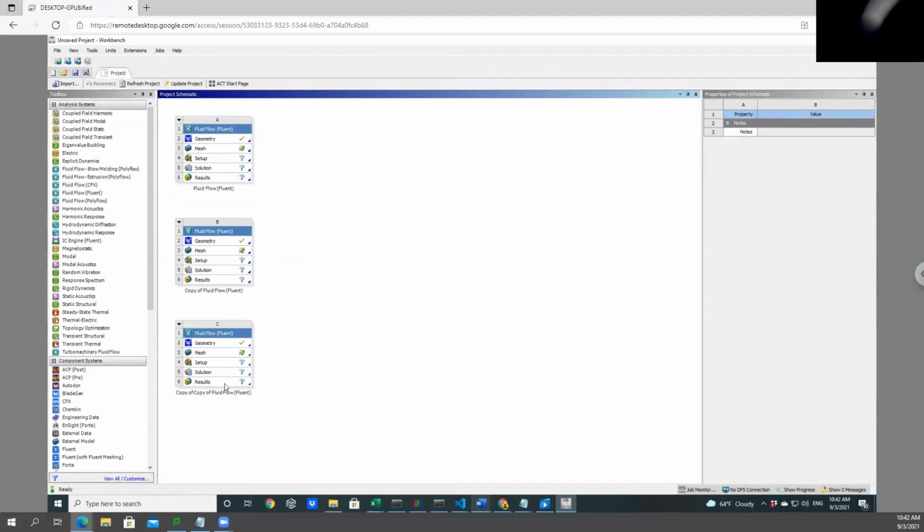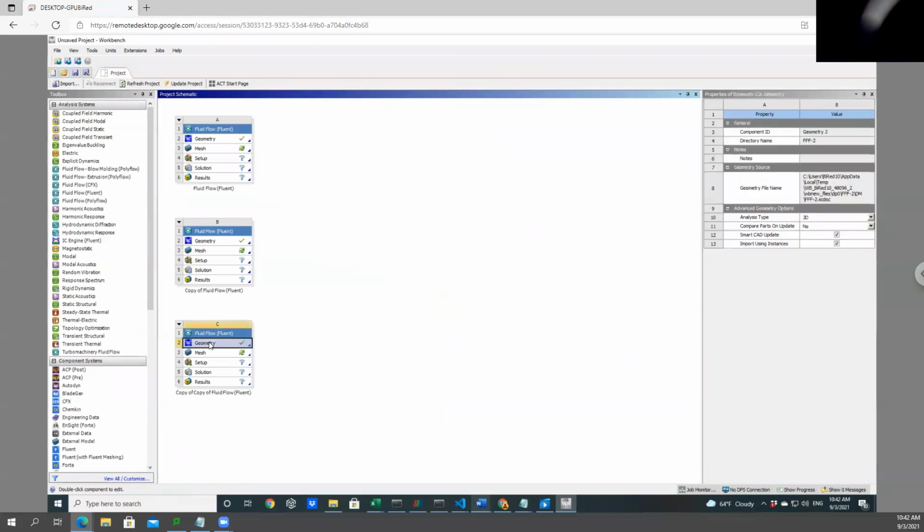And now we have this, right? This is also helpful in case you made a mistake creating the hemispherical geometry, the aneurysm set. You can just close your SpaceClaim and delete this project and start from here, right? You don't have to start from zero, right? That's also another relevant factor of doing things step by step, right? If you do something wrong in this part, just close it, delete it, and then duplicate this one, and you don't have to start from zero, right?